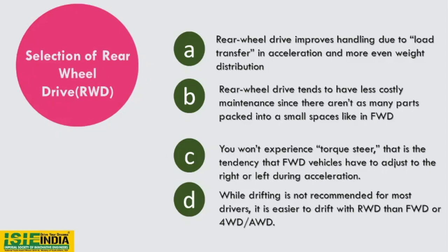It is not evenly distributed like in the case of rear wheel drive, and therefore front wheel drive also has higher repair and maintenance costs since they have to remove more parts for workable access, because it is so compact that you have to open the whole assembly while maintaining, but it is not the same case in the rear wheel drive because every part is distributed over the whole assembly.